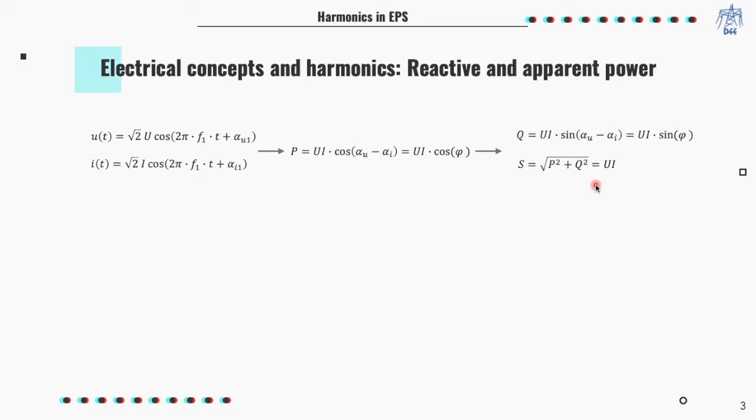Reactive power is not generated or consumed, thus, it is non-related to the physical work in a circuit. It is the power used to produce the magnetic and electric fields in conductors and capacitors. It is a power which flows back and forth but does not perform any useful work. The apparent power does not really characterize a physical phenomenon in an electrical circuit. It only indicates the total power involved in the electrical phenomenon in a circuit.